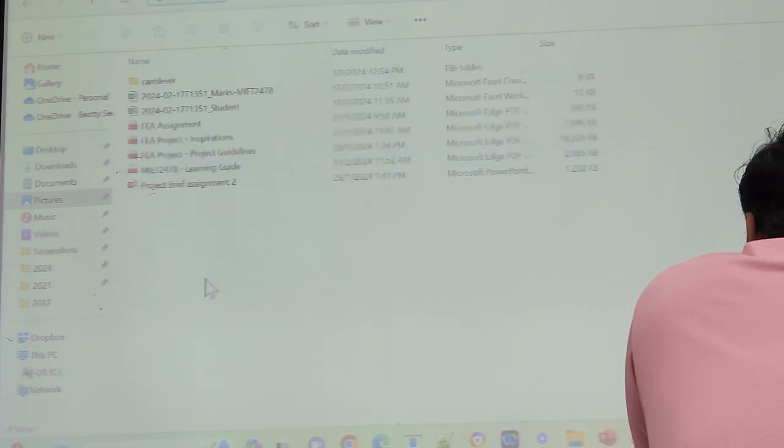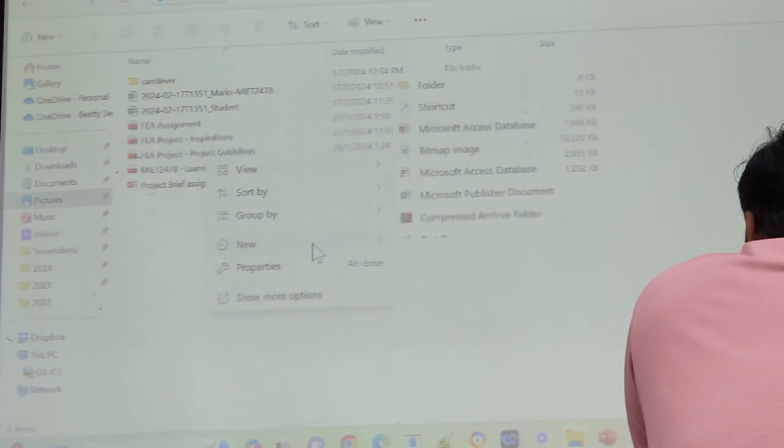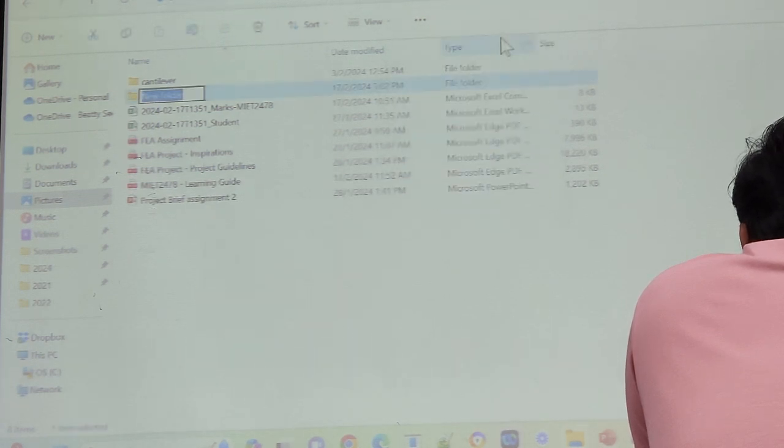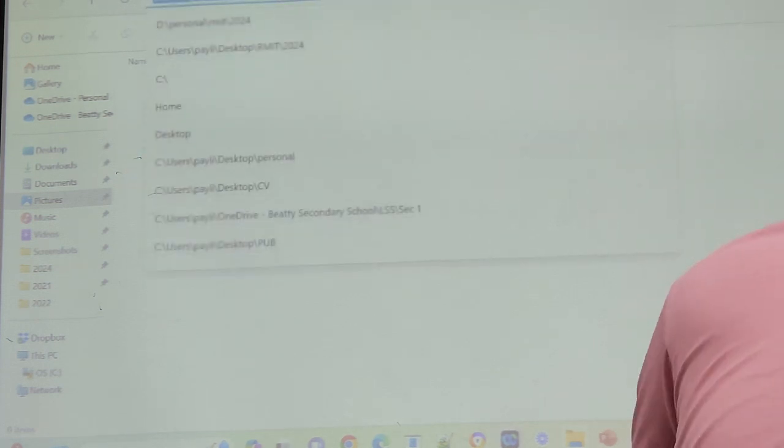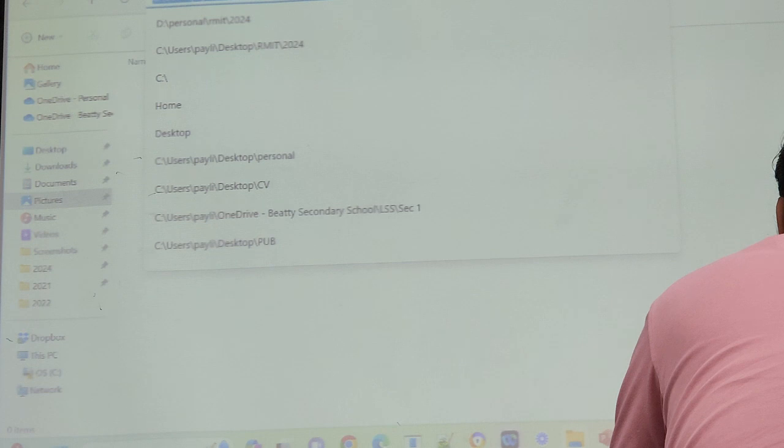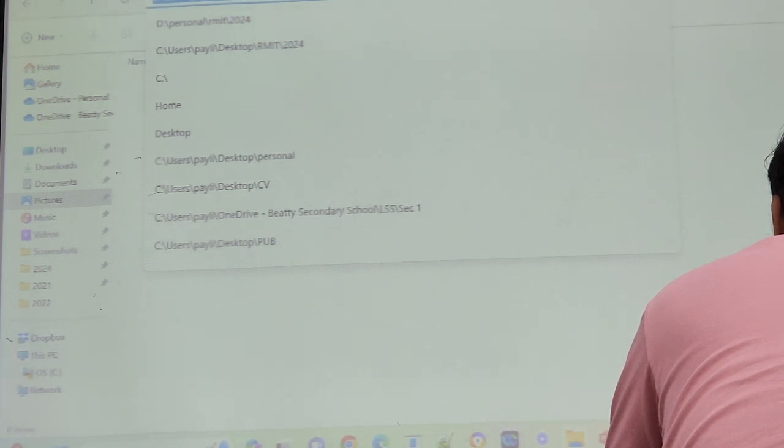This is important because all the files will be saved here. Remember we talked about this in Abaqus, right? If it crashes, it will come up with a journal file, a JNL file, and a replay file, an RPY file. Once you save it, it will be saved into a .jnl file. Both of these are Python scripts, so you can change the extension back to Python and run it in Python, and it will be very fast.